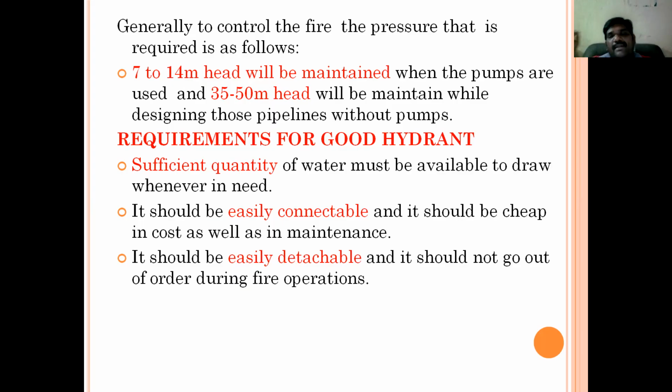Now, what are the requirements for a good hydrant? Sufficient quantity of water must be available, and they must be easily connectable and easily detachable. If getting the connection takes much time, in a fire accident where you need to fix the pipe to the hydrant to control the fire, huge damage may be incurred.